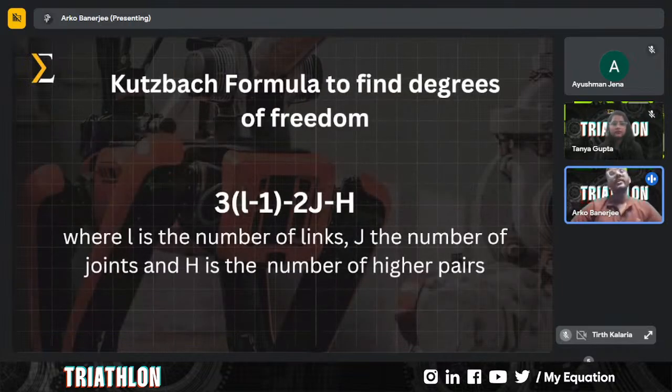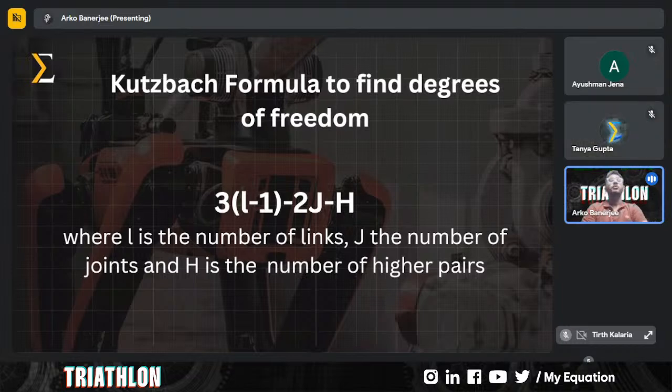Now let's come to a little mathematics. We won't dive deep into it. Very over-the-top mathematics. How to find the degree of freedom of a robot? I mean, if you just see a robot, how will you find the degrees of freedom? How will you understand what kind of motion it is? So the formula was given by the engineer Kutzbach, again from Czechoslovakia. The formula states as 3(L - 1) - 2J - H.